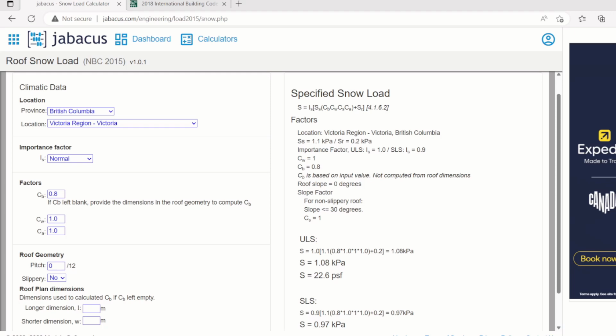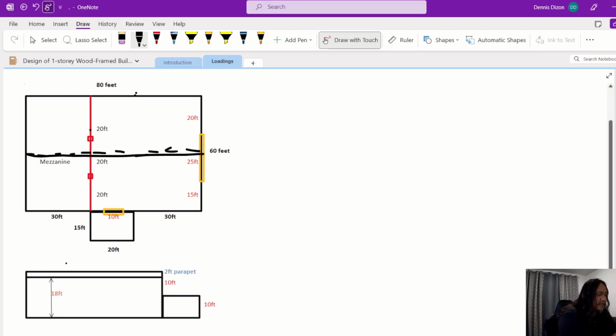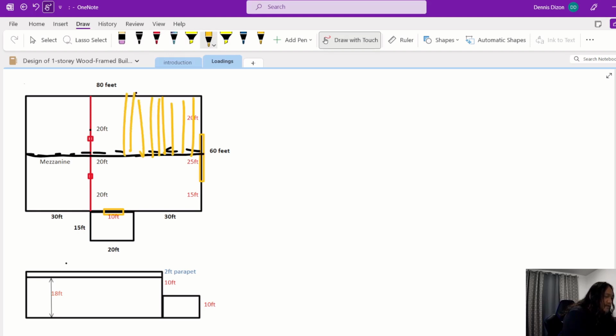So if you are restricted with the maximum height you can have for the truss, to make it shallower, you can divide the span by half, and then you introduce a girder truss in the middle, and then this will be your roof trusses.